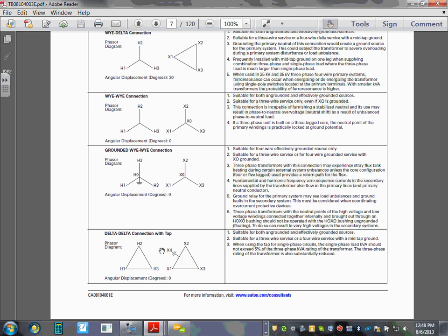So typically a delta from here and from the other side another delta. Take one part of the windings, tie it to the ground. That will give you 240 phase to phase, and between two phases and the ground and the neutral, it will give you 120. That's where the high leg is, and that's why a lot of us don't design it. And the third phase, between X3 and X4 here, will give you 208 that you're not supposed to use. I don't know, are you guys involved in that?